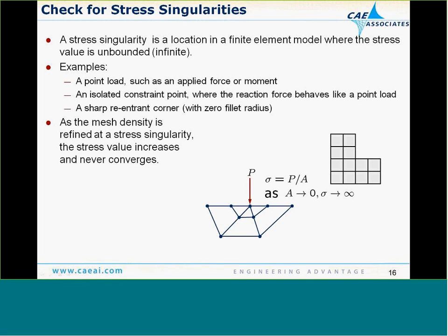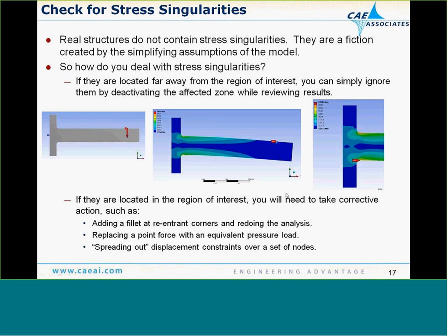Same thing occurs in a sharp corner. The stress is going to be infinite in that sharp corner. If I refine and refine the mesh around that corner, I will find that the stress will go up and up. So how do we deal with this?